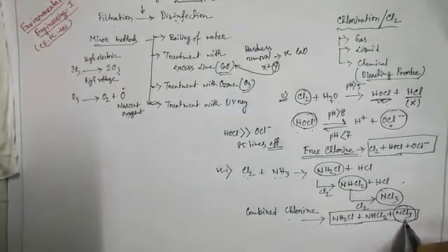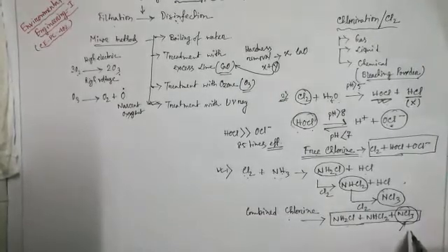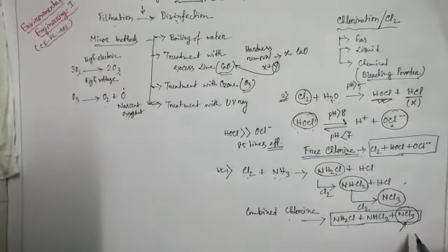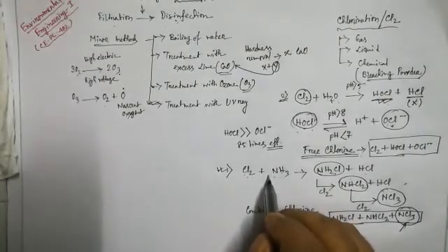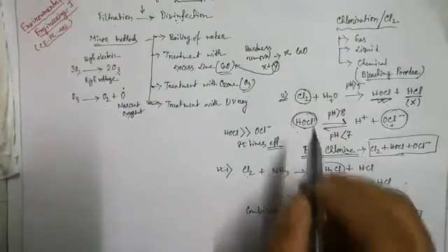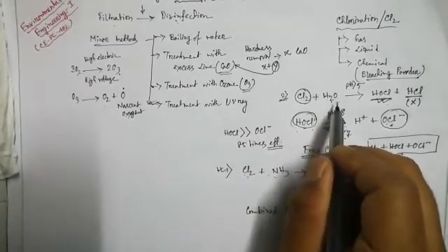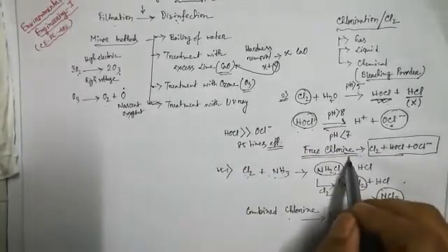Also always remember, especially for this one, NCl3, trichloramine, it is a carcinogenic material. Always remember, this has a bad effect. So always remove or minimize the amount of ammonia present in your water sample. Then there will be less reaction between chlorine and ammonia, and the maximum amount of chlorine will react with the water sample to produce free chlorine that will go for the disinfection process.